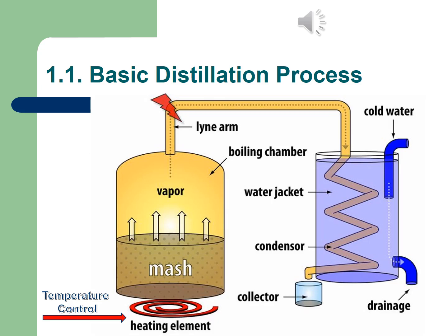Okay, looking at the different equipment that would be associated with a simple process like this, remember now that we have different boiling points. Okay, so if we can actually boil our mash, in this case it will be the sugar wash, so that will be again the sugar and the yeast that eventually formed the alcohols that are inside that sugar wash. Now by controlling the temperature closely to 68 degrees Celsius, the first thing that you will get out of the vapor, out of this mash, will be of course your methanol.